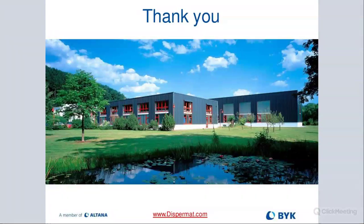Sure. So obviously, first, what I would say is let's get started on trying that on a smaller scale. Come up to the lab, bring a small quantity of your material, and let's run it on a dispermat and then mill it with the TML mill in a small volume. Then we're going to look at the results. We're going to look at the milling time, what bead size we use, the screen mesh size, and all that. And then also the diameter of our dispersion plate. So we're going to record all these different parameters and dial in what combination gave us the best possible performance.